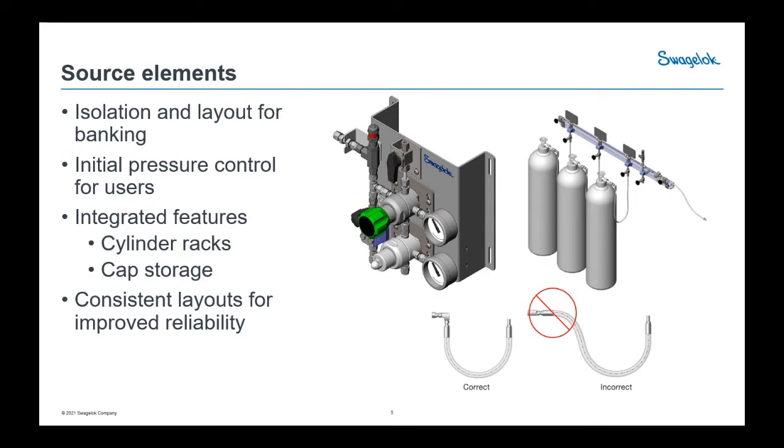So the primary goal here with your initial pressure reduction is to reduce the pressure initially and get that transport pressure down so that if you end up springing a leak somewhere down in your system, you're not losing as much of your gas. This can be a trade-off though, as you're likely going to have to increase the size of the line that's transporting that gas.